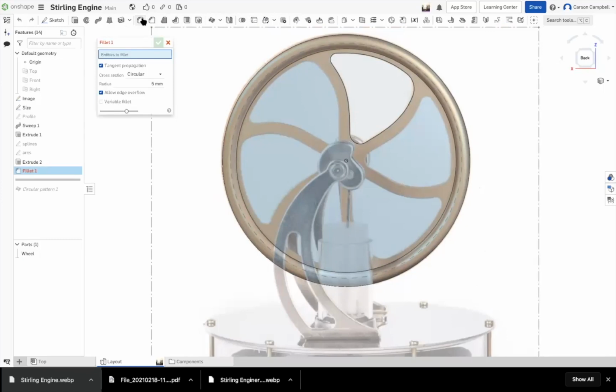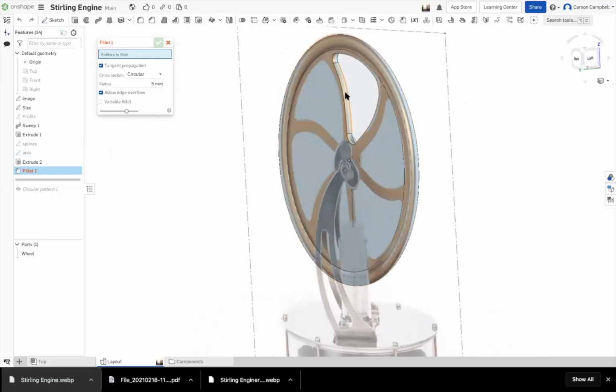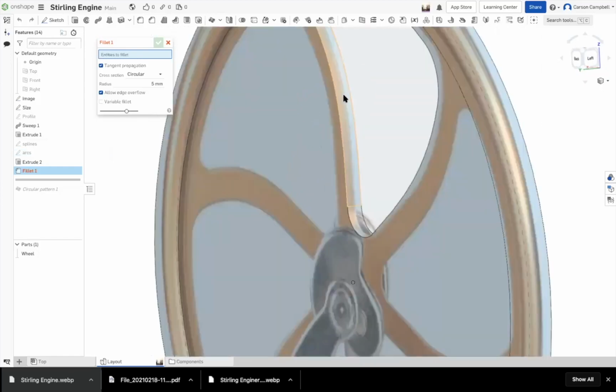Okay. Well, okay. So there's sketch fillets and there are solid fillets. Okay. Now, what's the reference for this fillet? No, no. So what I want you to do is I want you to rotate it so that you can see one of the faces. And that one face right there, I want you to pick the face. Okay. Does that work? And now zoom in because it's picking the edge. Okay, and now pick that. And change your fillet to 1, radius 1.